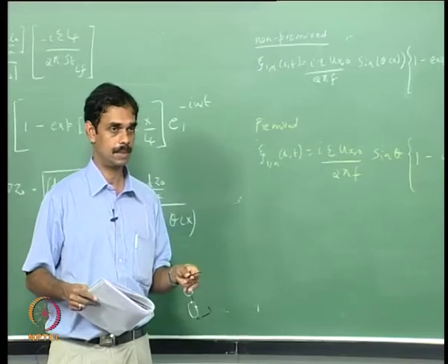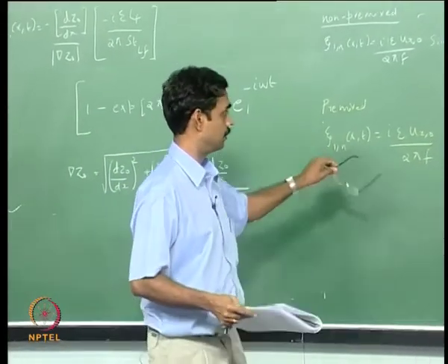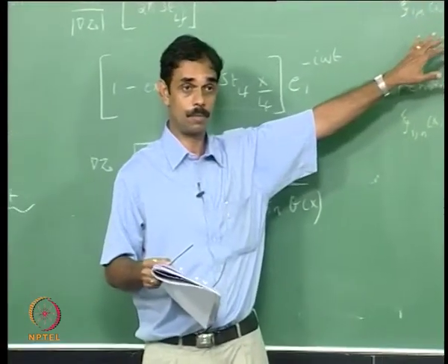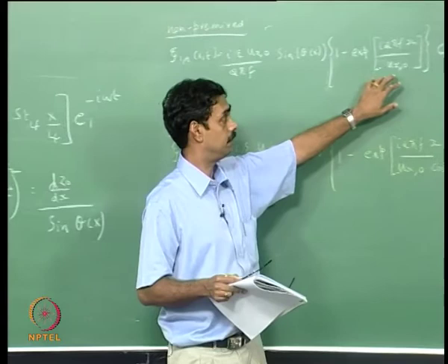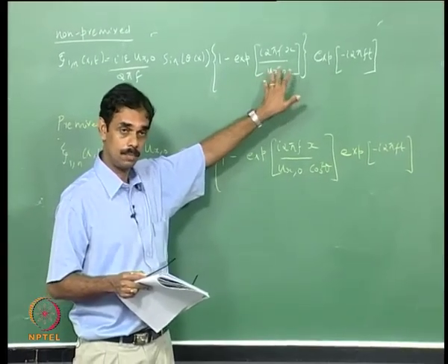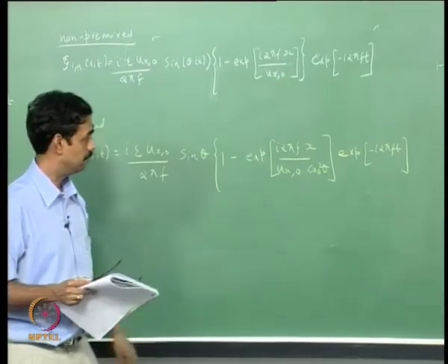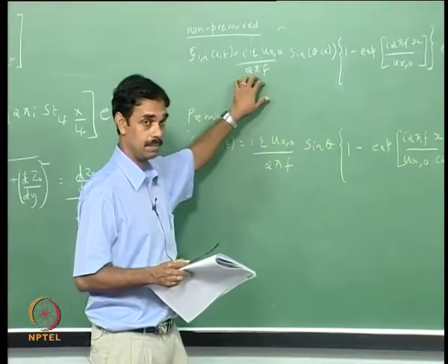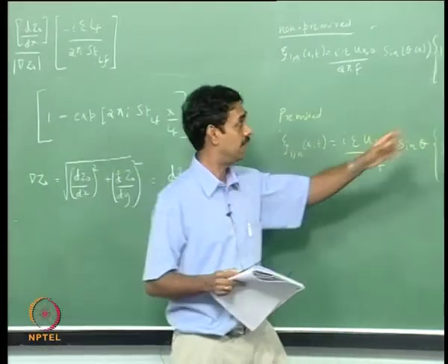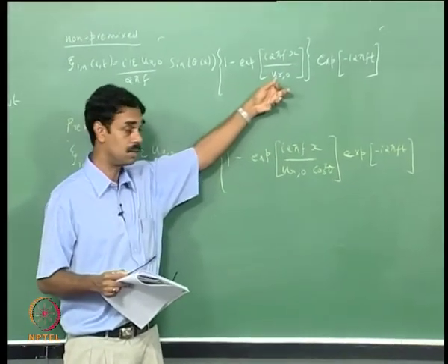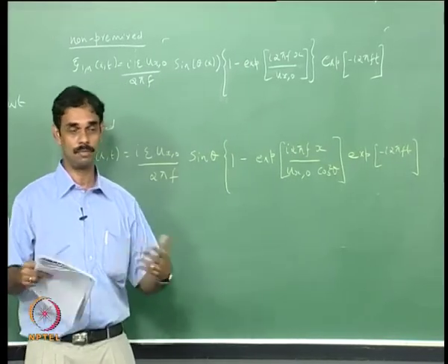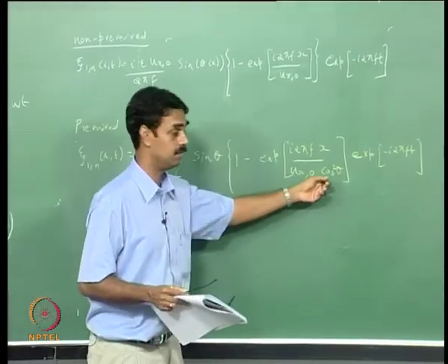Okay, I will pause for a minute, you can look at the formula. The diffusion flame or non-premixed flame does not propagate, so you have the speed as the convection speed itself. Wrinkles will be propagating only with this convection speed for the non-premixed flame. For the premixed flame, the flame is trying to propagate and then the flow is trying to come in. So you won't get exactly ux0, but something that depends on ux0 and the flame angle, because the flame angle reflects the flame speed. So that is why you have this difference.